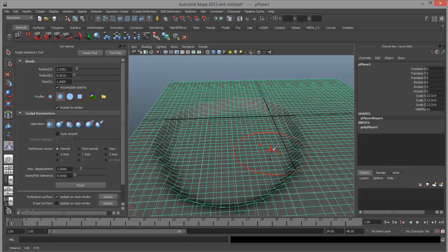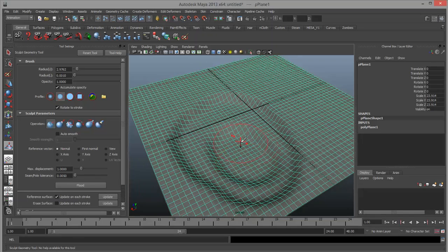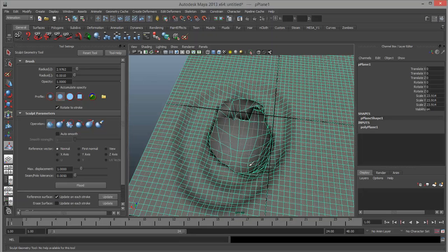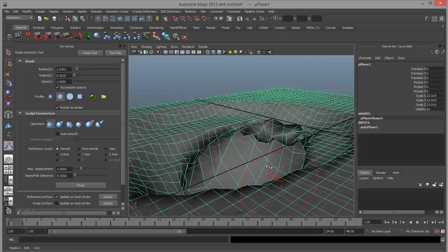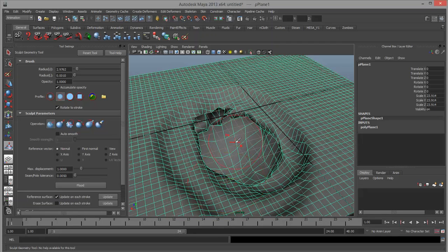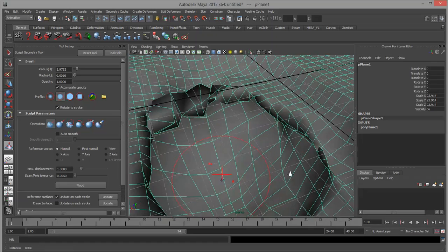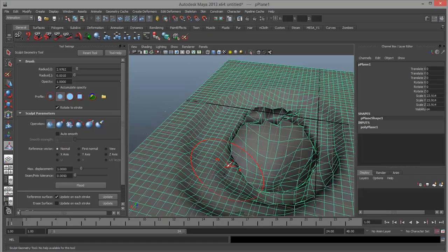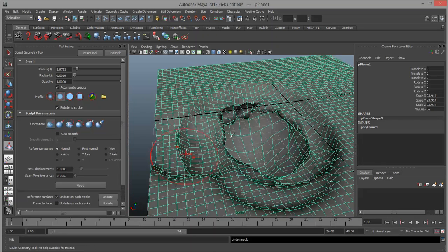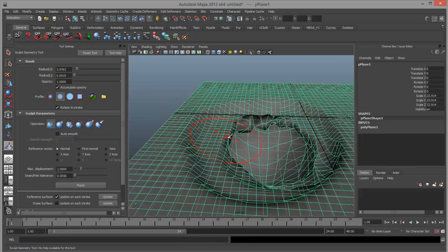But there you can see we've got this Sculpt tool, and if you click and drag multiple times, it goes deeper and deeper, but eventually you get this kind of ugliness going on here and like, ooh, tumorous growth going on there. What's happening is that the direction it's pushing is the normal direction, as in straight perpendicular from the face as it began. So when we get slopes like these, the normal direction is now diagonal. And so if I push on those, diagonal is the direction it wants to go, and as they move more and more, they get more and more distorted.